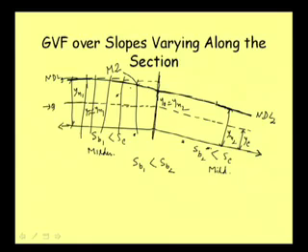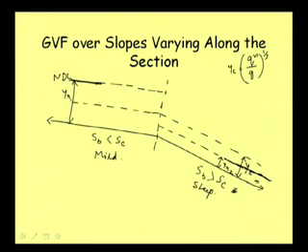Unlike the earlier case, where this was subcritical flow, so this disturbance was not influencing this one. But here it is supercritical flow, so the disturbance at this point will be influencing the flow. And as such, we can say that this section at the junction is the control for this downstream flow portion also.